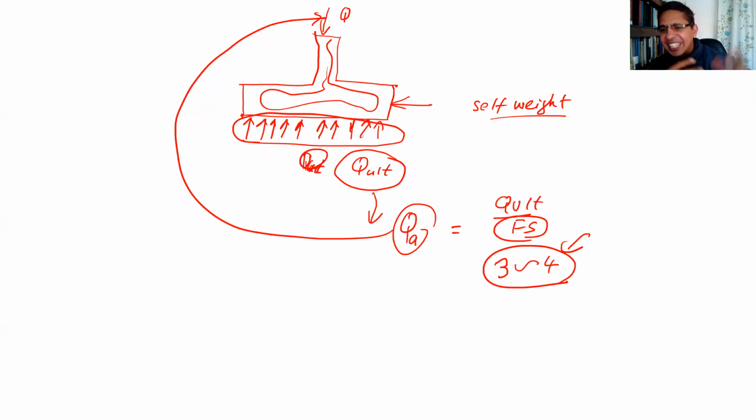That is the reason why we have a very big factor of safety in soil engineering, because we don't do detailed calculation. Really, we don't know how the soil varies; a small part here, just close to it, is different. So we try to accommodate overall. That is the reason we didn't use self-weight of concrete here. But you can, if you want to be accurate. You just need to add it to the given load.